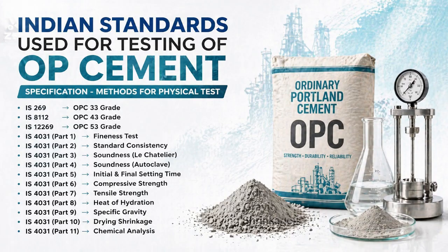Now here we will see some key Indian standards that govern ordinary Portland cement manufacturing and its quality parameters. IS 269 specification is for OPC 33 grade. IS 8112 is for OPC 43 grade and IS 12269 is for OPC 53 grade. Above specification gives requirements for OPC manufacturing, chemical composition, and physical properties of this grade, including their strength and quality requirements.